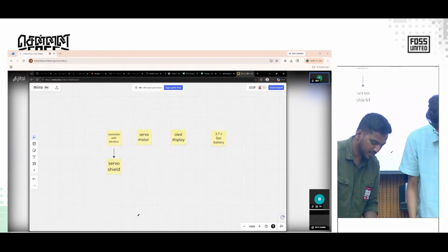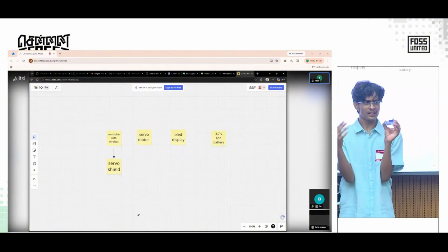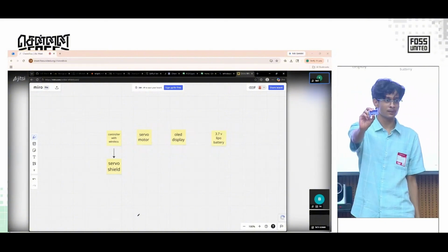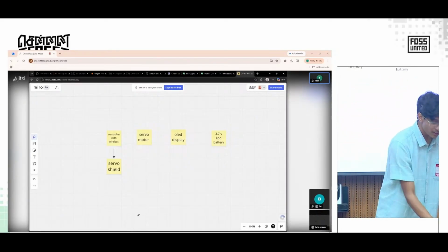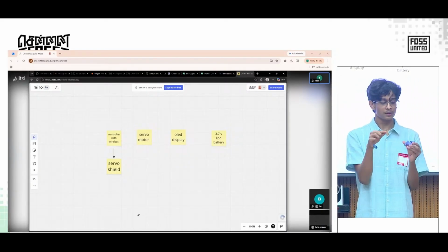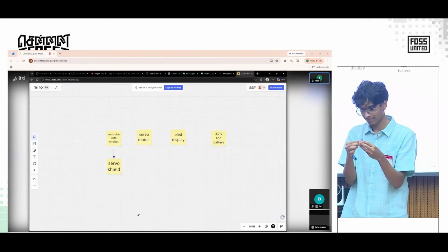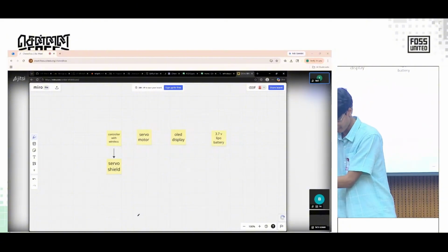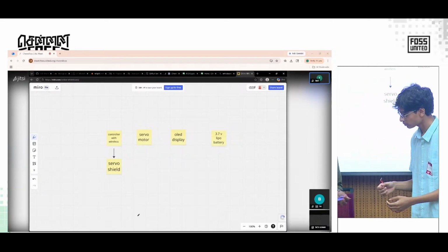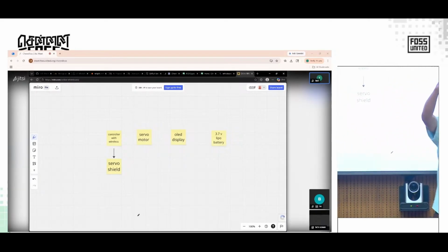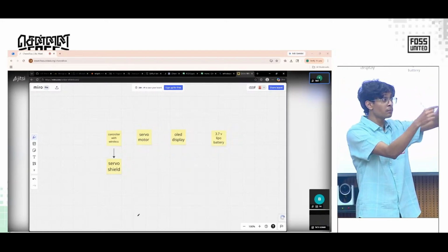Next step. So yeah, this is the base of our tank. This part is what holds the servo motors. So this is very simple. You actually might have already figured it out. What you do is you take the servo motor, you hold this part and you push it through this hole right here. So this is how it should look. The wires should go through this hole like this from the inside.